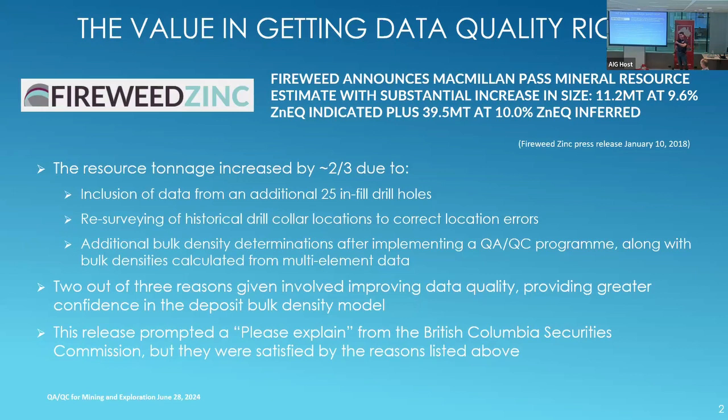But in my own history as well, there was an example where we were able to provide, back when I was a consultant, a 10% upgrade to their resource, just on the fact that they had used an XRF method, but their ore was a bit harder than they'd expected. And because the grind size was not the same size as what the XRF instrument had been calibrated on, they were undercalling their result on the initial results. So you never know what might pop up, right?